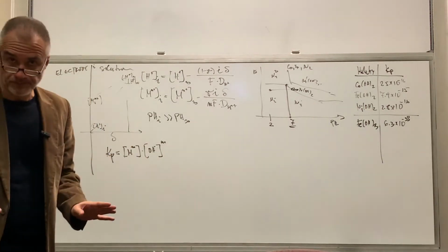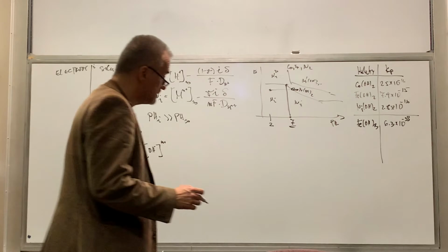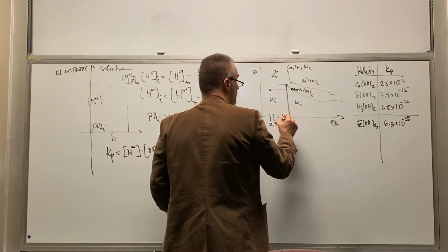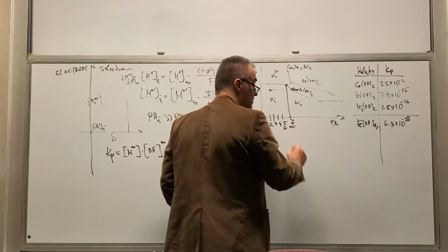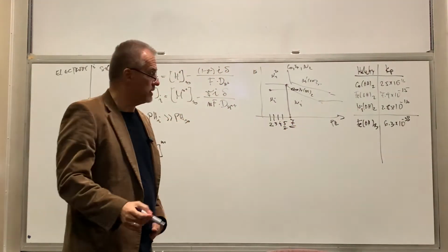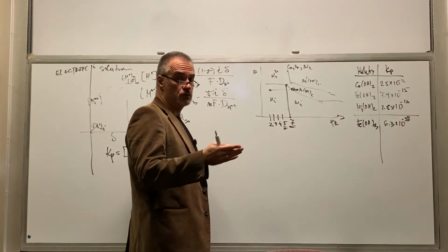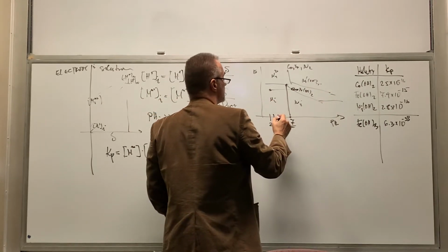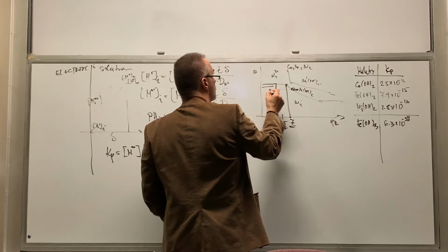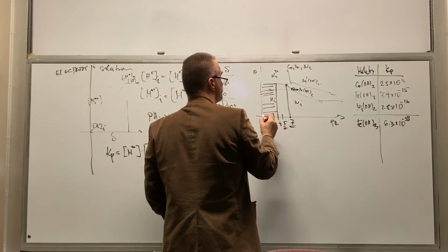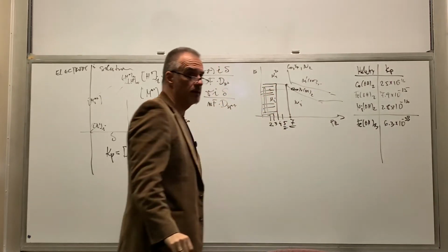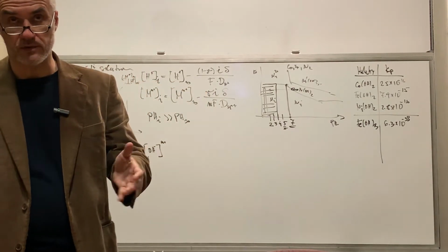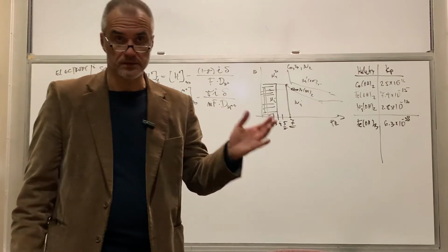It is possible, and especially it is possible if you do the deposition with pH 3, 4, and maybe 5, already you're pushing the limit. But in general, what we really do to avoid the problem is that we like to stick to a pH below 4, right? We like to be with pH below 4 when we do electrodeposition of these types of alloys with cobalt, nickel, and iron, magnetic films and so on.